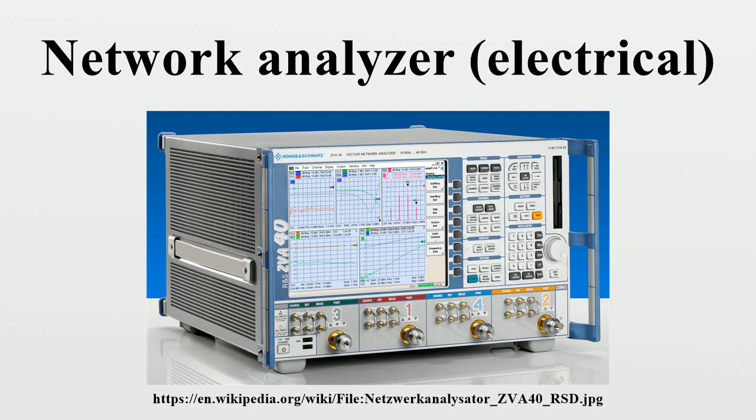When SW1 is set to position 2, the test signals are applied to P2. The reference is measured by RxREF2. Reflections from P2 are coupled off by DC2 and measured by RxTEST2, and signals leaving P1 are coupled off by DC1 and measured by RxTEST1. This position is appropriate for measuring S22 and S12.